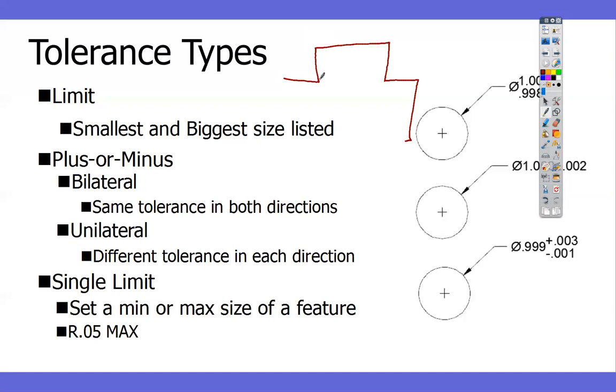So what I used to always do, anytime there's a corner like this, I would add a little radius. That way the laser would slow down a little bit, but then keep going. It would never stop. If there's a hard corner, it's going to stop, even if it's just a little tiny bit. If there's a tangent, it just keeps going. Lasers, water jets, plasmas, all do the same thing. And so I would add a little radius in there that they wouldn't see in the final thing. But it made it easier to make it, and it wouldn't have that big burnout there or anything.